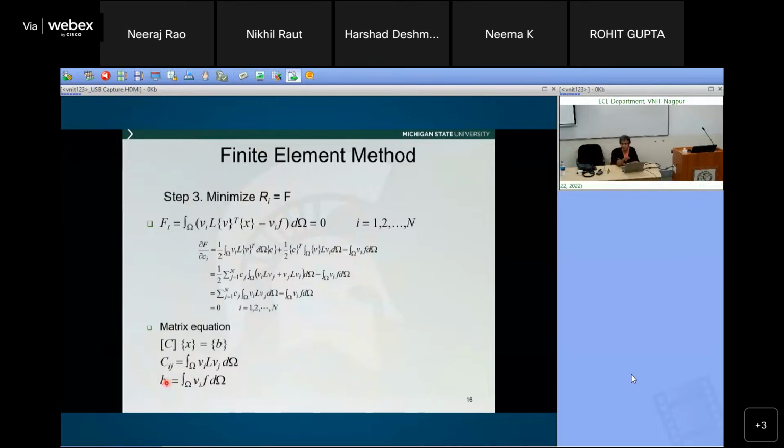In fact, when we do pulsed eddy current, the pulse is a pulse. If you take the Fourier transform, I know exactly what the Fourier components are. Then I do the finite element at each frequency, take the inverse Fourier transform, and calculate my time domain signal. That's a very common way of doing it. You guys know all about the modeling, really. I don't think I need to spend too much time. So this modeling is in the frequency domain, for a single frequency only.